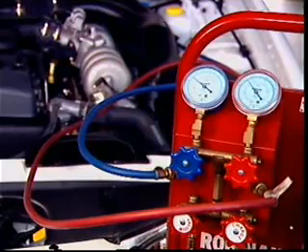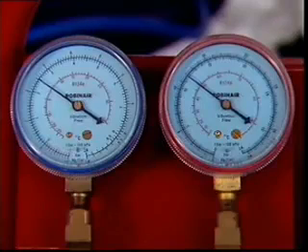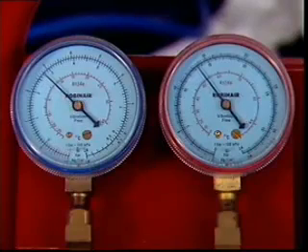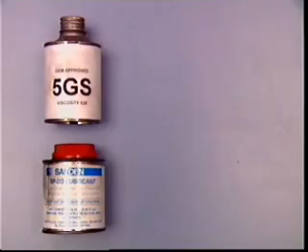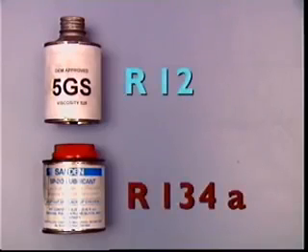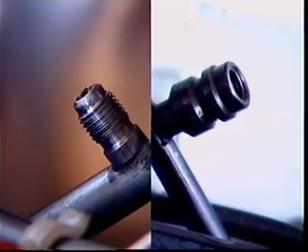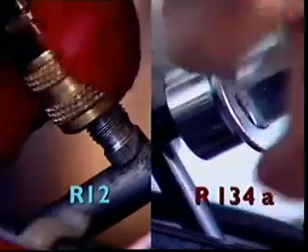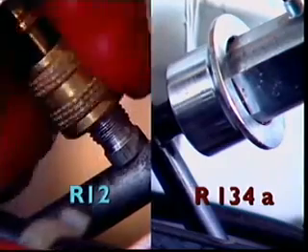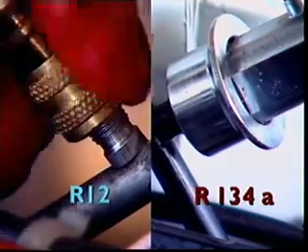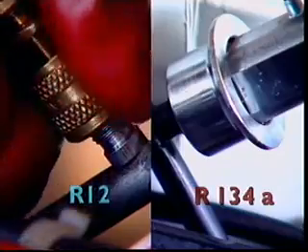The only difference being that its operating pressures and temperatures in the evaporator and condenser are slightly higher than for R12. There are important differences in their chemical properties. Unlike R12, R134A is not soluble in mineral oils, so new compressor lubricating oils have been developed. To prevent the wrong lubricant or refrigerant being installed during servicing, the service ports on air conditioning systems have been changed so that the service equipment for an R12 system cannot be connected to an R134A system.